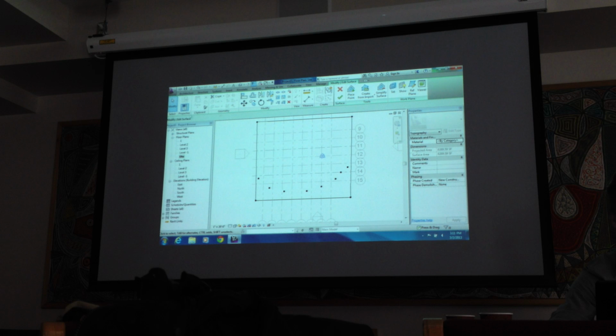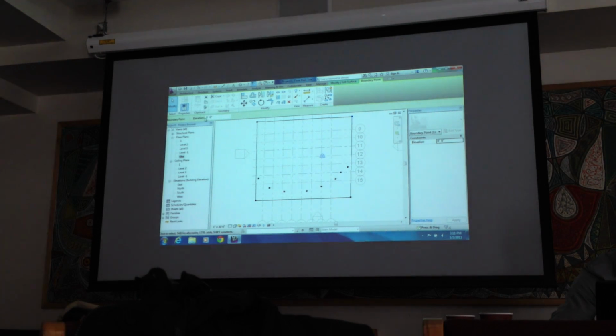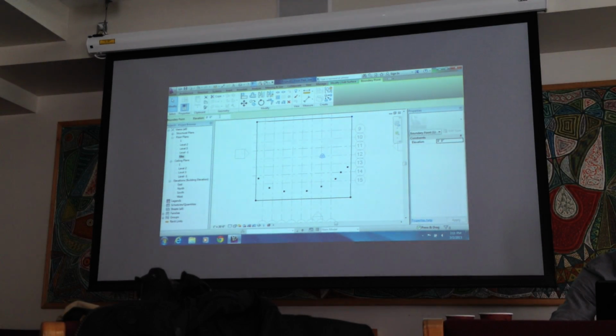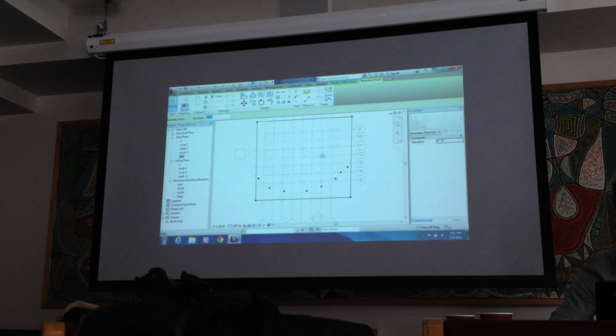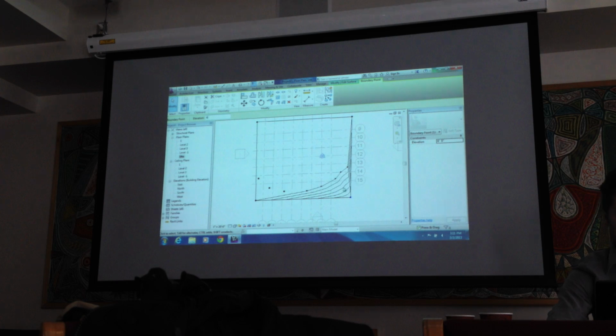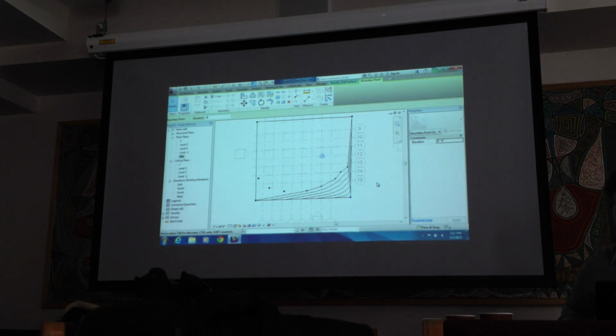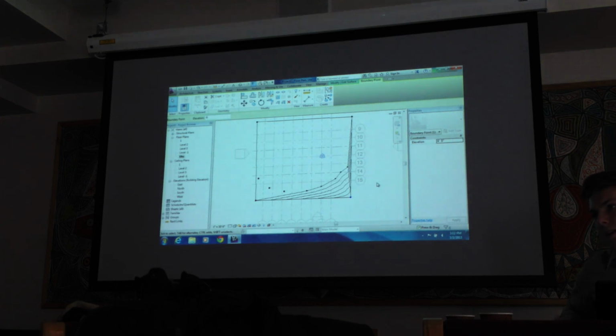After you finish placing points, you click the modify button on the left again, and it'll allow you to select individual ones. As I click individual points, you'll see at the upper left portion of the screen that it says elevation is 0. But let's say I want this side to raise up by 6 feet or so. So I'll click elevation, it says 0, I'll type 6, and I'll raise it up by 6 feet. There we go.